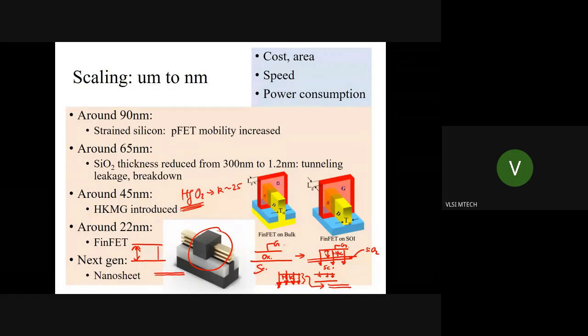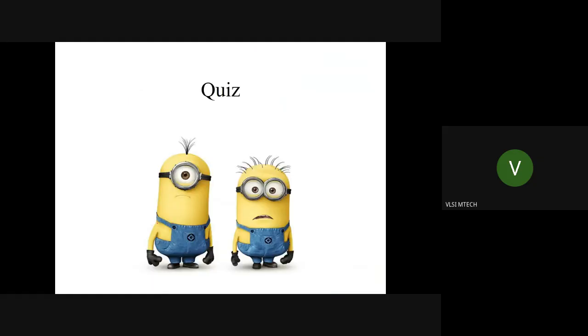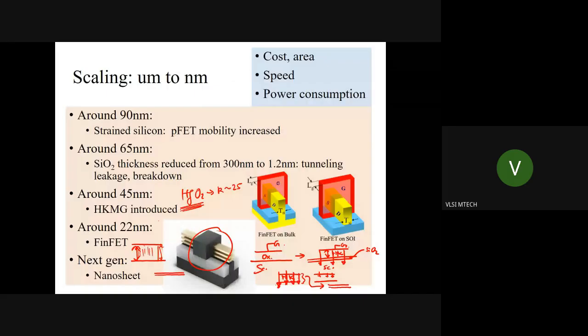Now, the benefit of keeping a thick oxide is that the field across the oxide is dependent on this thickness somewhat. So for the breakdown field, you need to apply a larger voltage, that is one. And also because of this thick oxide, there'll be less leakage and all of that coming into play. So that's good. So we are retaining the gate control, but we are negating all the effects of thin oxide like leakages, right? So that is what we are doing.